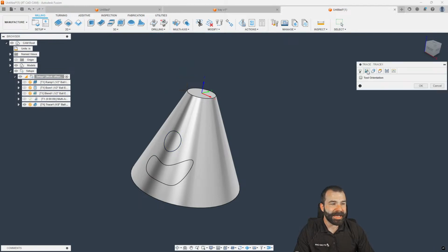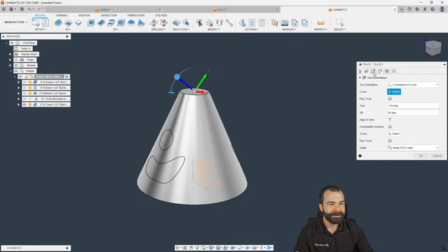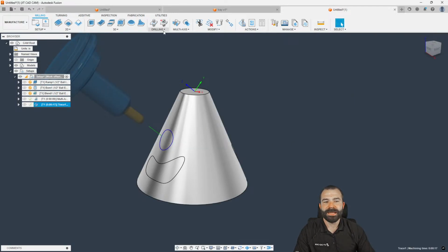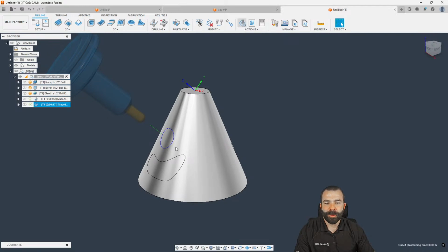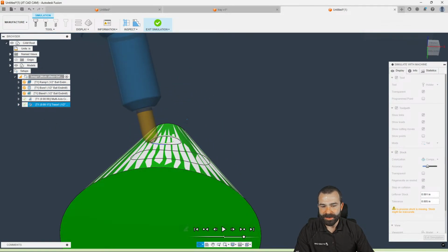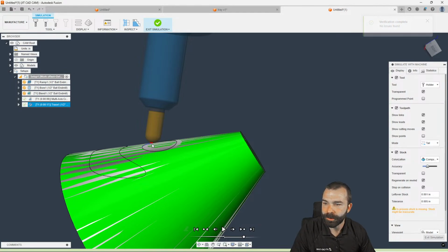We go back to trace. Obviously, trace has tool orientation, which means it's still 3-axis, right? So if I did the same part based on multi-axis tilting, what you're going to see is I'm going to very generically tilt my Z-axis here. Again, I use my curve selection, same tool. The difference is when I simulate this, we stay at that fixed angle, and we're basically going to gouge this part, because the whole time that tool is pointed at our part, we're not actually tilting to get away from the radius that's engaging in that part, right?